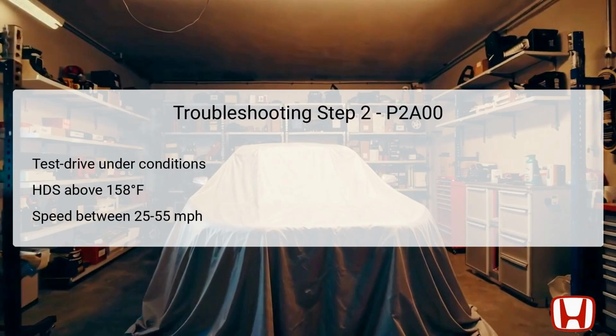During this drive, the vehicle should maintain a transmission setting of drive, D, and achieve speeds of 25 to 55 miles per hour, 40 to 90 kilometers per hour, for a duration of 5 minutes. Adhering to these conditions allows the PCM and AF sensor to perform optimally, ensuring accurate diagnoses following the drive.